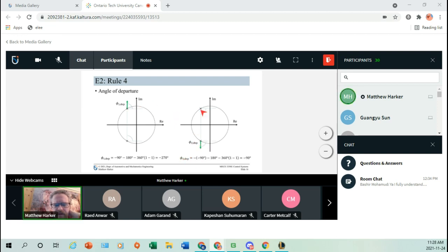And at the other point, the angle condition, as I said, is valid by using the poles as test points. So again, everything has to add up, and that just means by solving for that other departure angle, we get minus 90, which is then pointing downward in the other direction.